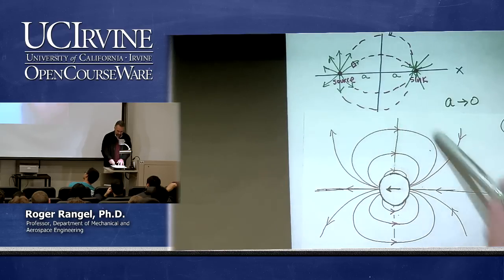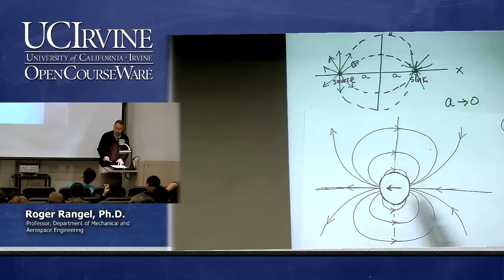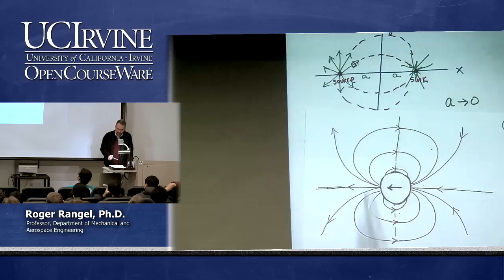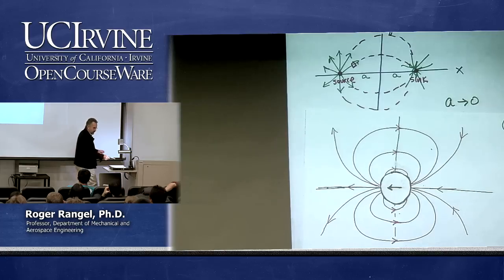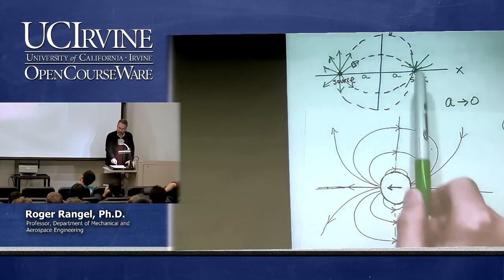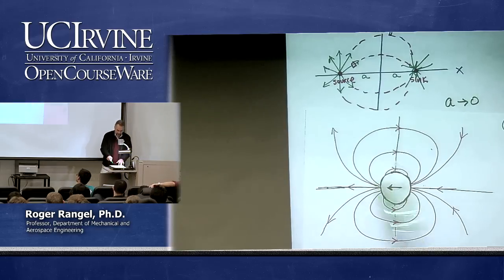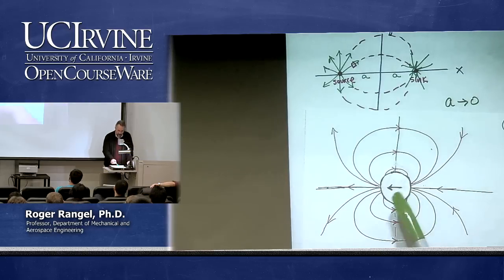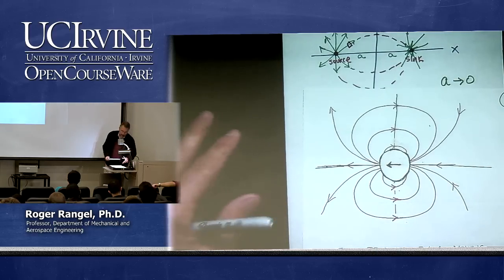But of course, by conservation of mass, it suctions in fluid from the back. So as it moves from right to left, again, there is fluid coming from the back that is catching up with the cylinder. So that's the physical interpretation of what the doublet is. It's just the transient, the unsteady motion of a cylinder. In this case, from right to left, because I put the source on the left. If I had started with the opposite view, with the source on the right and the sink on the left, this would look exactly the same, but it would be going the other way. The cylinder would now be moving from left to right. So that's an important application of what the doublet is. It's the flow produced by a moving cylinder, right? Unsteady flow produced by a moving cylinder.